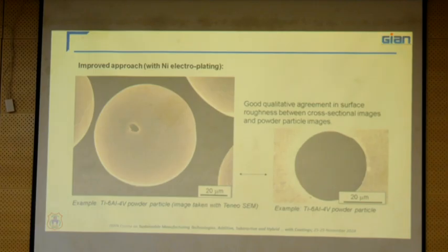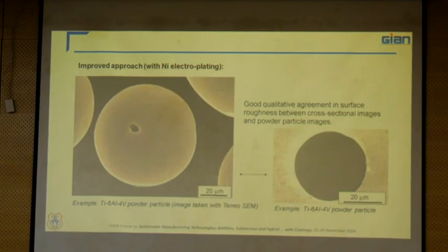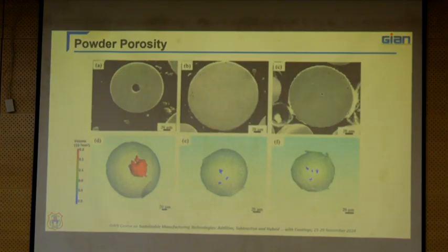And if you see, this is the porosity which you can easily observe in your scanning electron microscope. But do we know whether this porosity is only at the surface level or has any volume? In the scanning electron microscope we can see only the porosity visible on the surface. How much depth, what is the volume, we do not know. For those things we need to go with X-ray CT tomography to understand the volume aspect of your porosities.